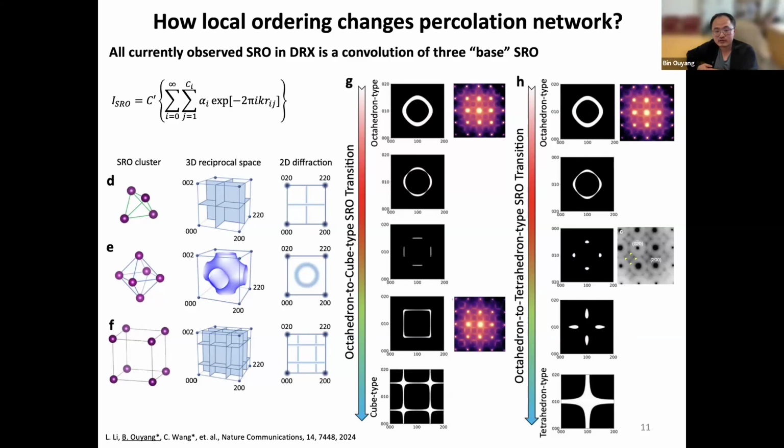Yeah, very good question. It's definitely temperature dependent. I'll take these two as an example, the round one and the square one. The square one can be obtained by quenching the material at different speeds. That means if you limit the kinetics, sometimes some local structures will decrease in population and some will increase. That's actually the experiment we tried in this paper. We anneal the material for different times or quench it at different rates. It's also sort of controlled by the elements as well.